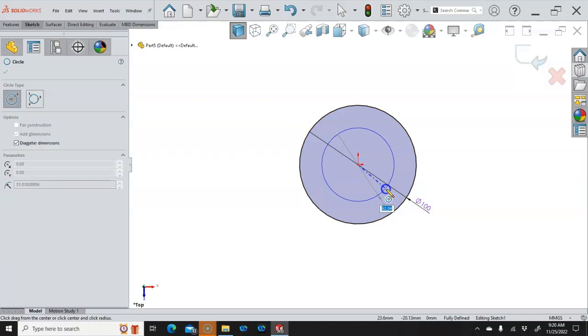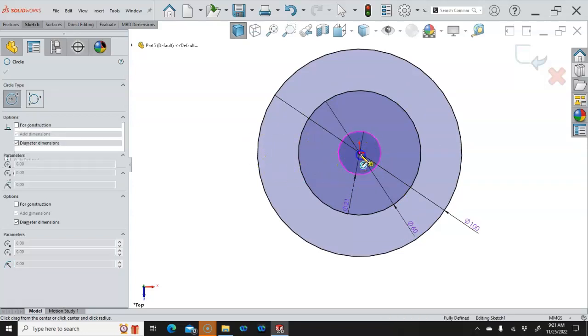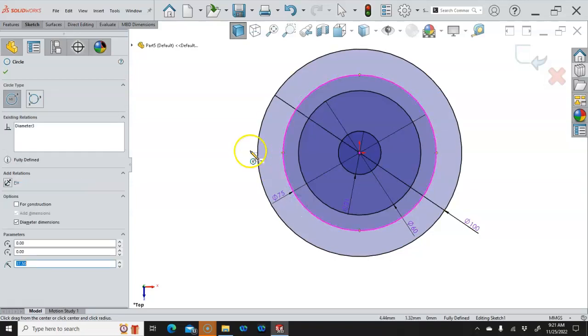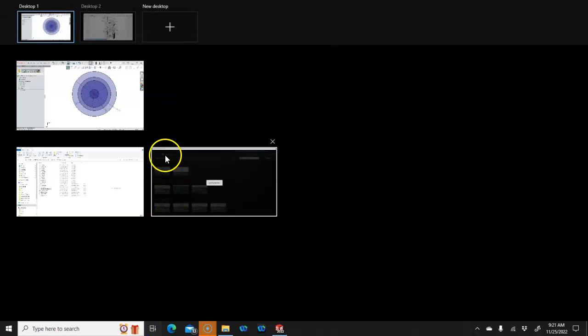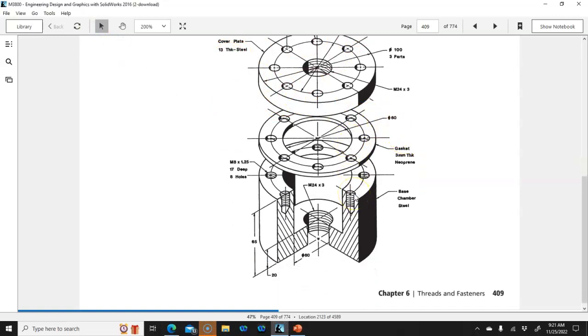Okay, I've got my dynamic input on, so let's see, we're 60 there. And then I'm going to go ahead and include the minor diameter of the thread at 21. And then we need a base circle of 75. I think it was 75 anyway. All right, 75 all holes, 60 on the inside.